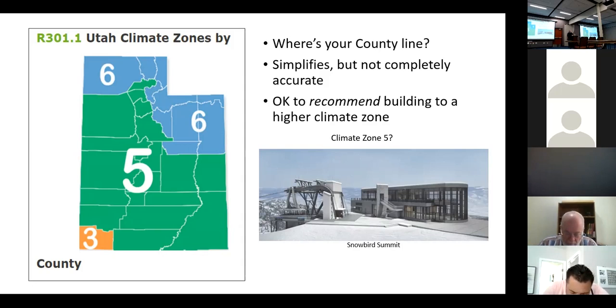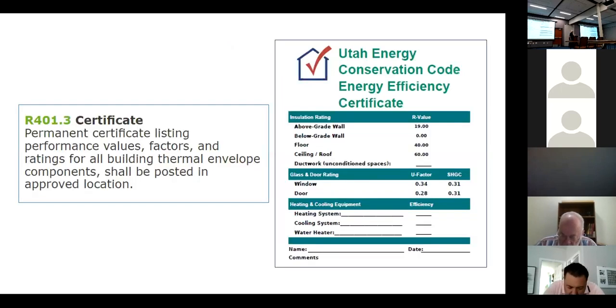So what do we recommend? This is really climate zone 7 or 8, because the design temperature there for HVAC from ASHRAE is -15. And the wind is high because you're right at the top. So that's really the case, but we can't enforce more than climate zone 5. The code official is the last one. You could enforce it. I could not enforce a higher one by code; I cannot say no.